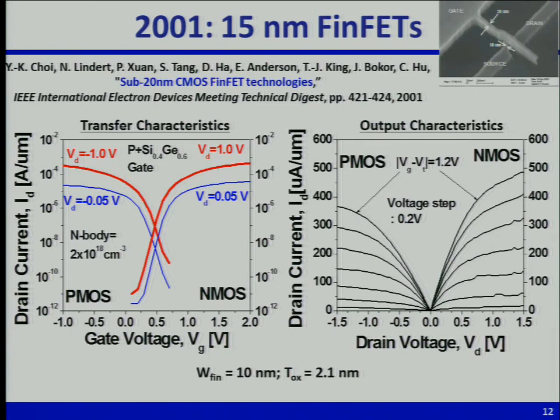But notice here, for the same amount of gate overdrive, gate voltage minus VT, you don't see that much difference between the NMOS and PMOS. And actually, indeed, in Intel's 3D transistor CMOS technology, the P-channel devices have pretty much just as much on-state current as the NMOS devices. Can anybody explain why?